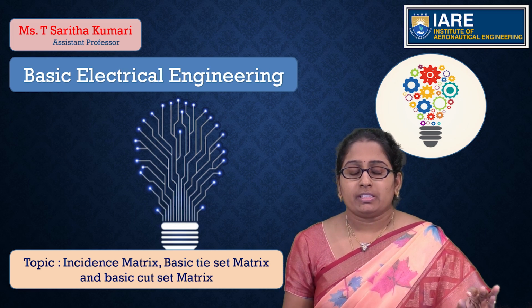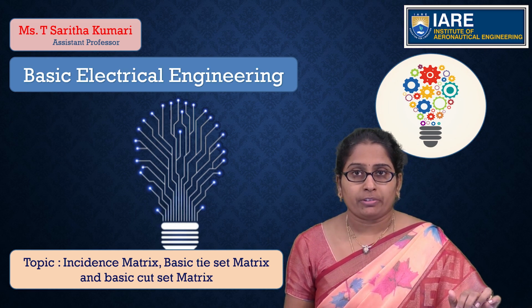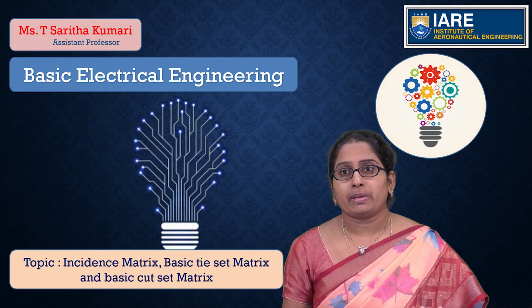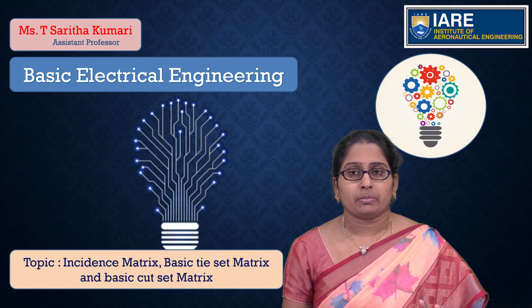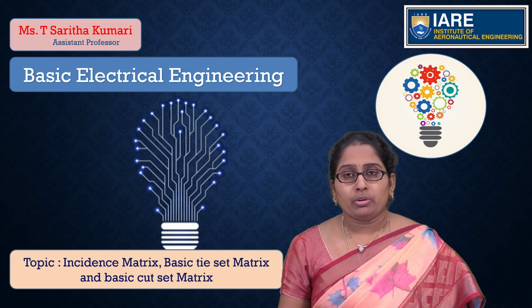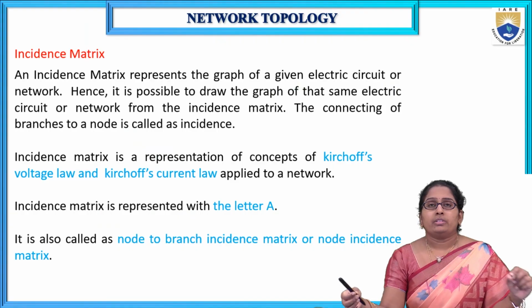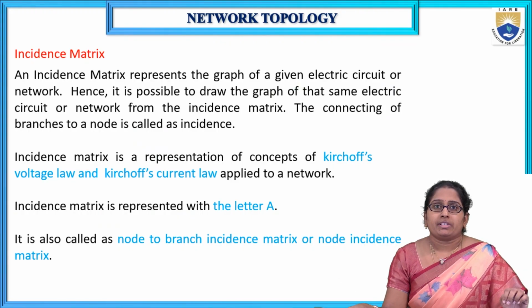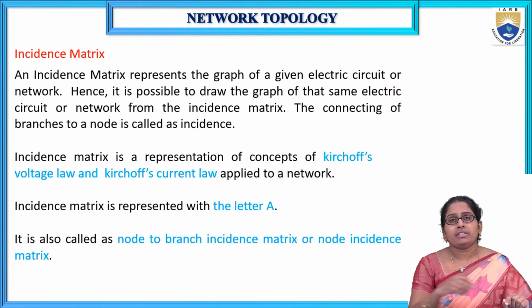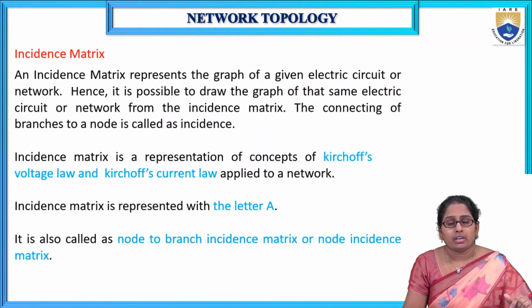Today my topic is under network topology: incidence matrix, basic tie-set matrix and basic cut-set matrix. So first, about the incidence matrix. What is meant by an incidence matrix? An incidence matrix represents the graph of a given electric circuit or network.